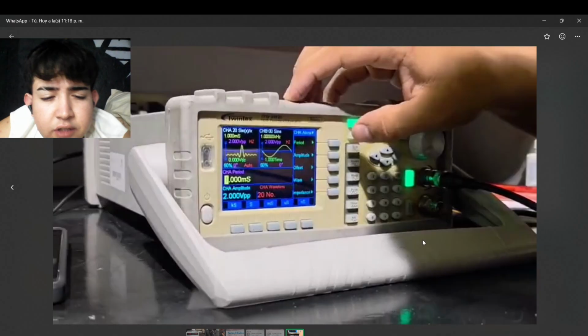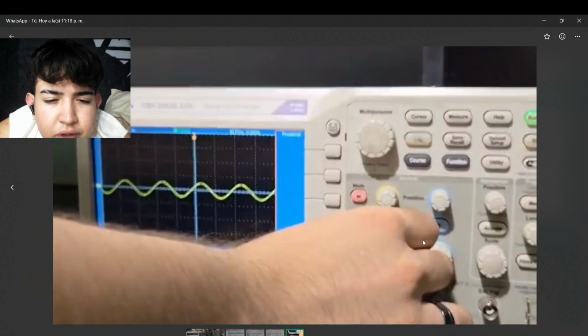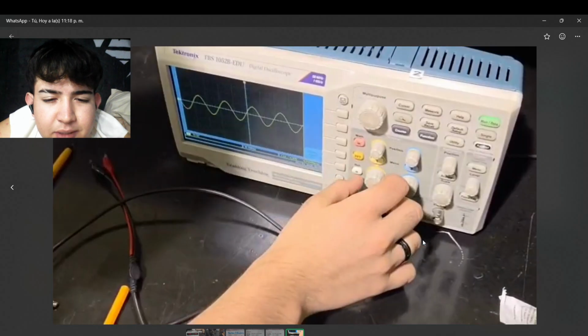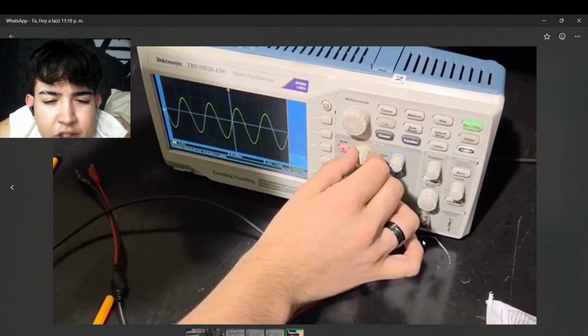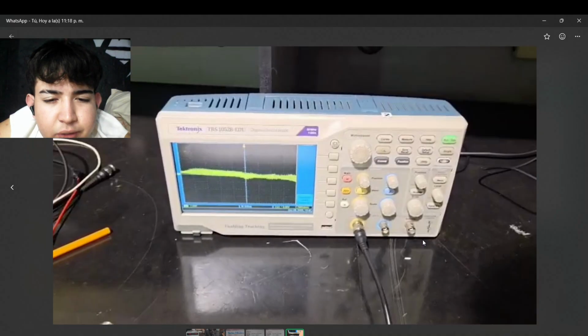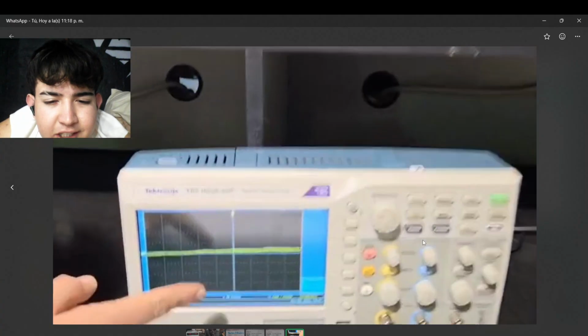Step 4. Detailed analysis of the oscilloscope menu. A deeper analysis of the oscilloscope menu was performed, exploring the options in the measure, acquire, display, cursor, and utility menus. The key functions of each are described below. Measure menu. Automatic measurements such as Vpp or RMS voltage, frequency, period, pulse width, and duty cycle facilitate signal analysis.